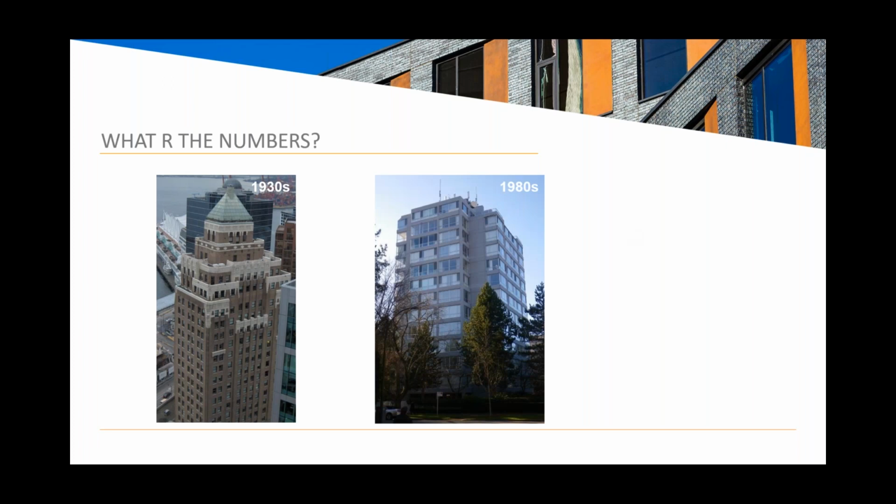So building number 2 is over 35 years old. It's a concrete structure. It is exposed on the exterior. About 50% is concrete and has a steel framed wall inside of that. Inside that steel frame is where the insulation is. And the windows are aluminum frames. So the aluminum windows that you're seeing there are not thermally broken.